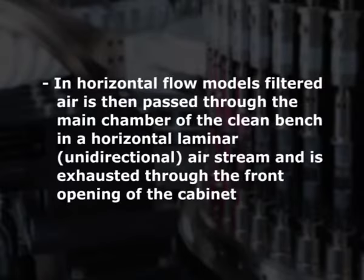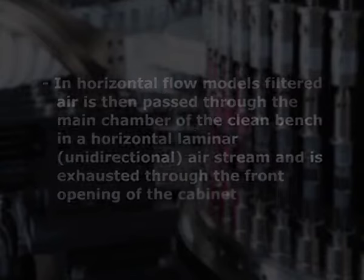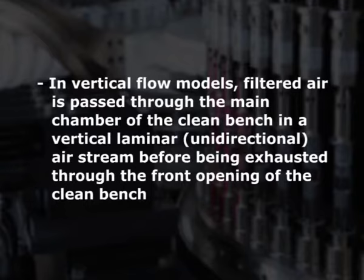In horizontal flow models, the filtered air is then passed through the main chamber of the clean bench in a horizontal laminar unidirectional air stream and is exhausted through the front opening of the cabinet. Whereas in the vertical flow models, the filtered air is passed through the main chamber of the clean bench in a vertical laminar unidirectional air stream before being exhausted through the front opening of the clean bench.